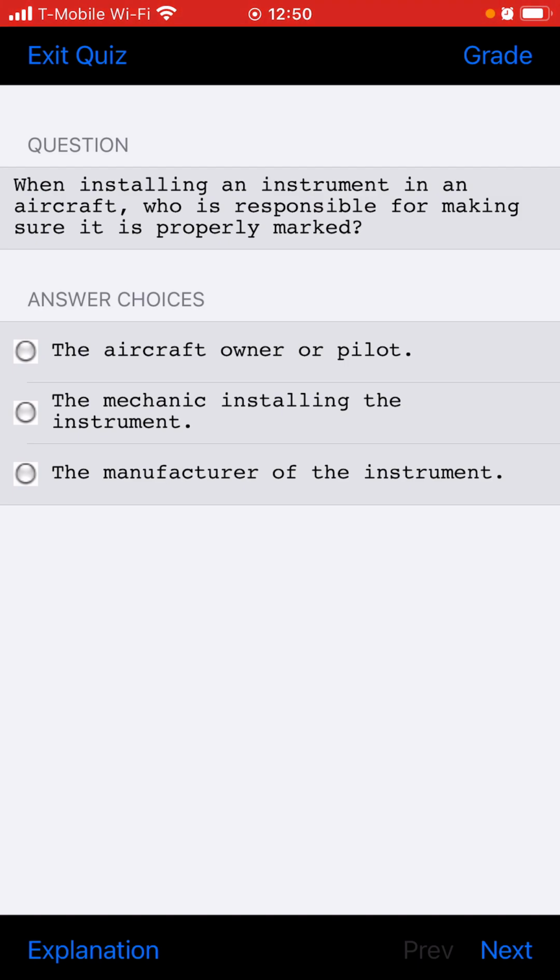Describe several methods of pressurizing a hydraulic reservoir. Engine bleed air. System pressure acting on a small piston in the reservoir. Using variable displacement hydraulic pumps.